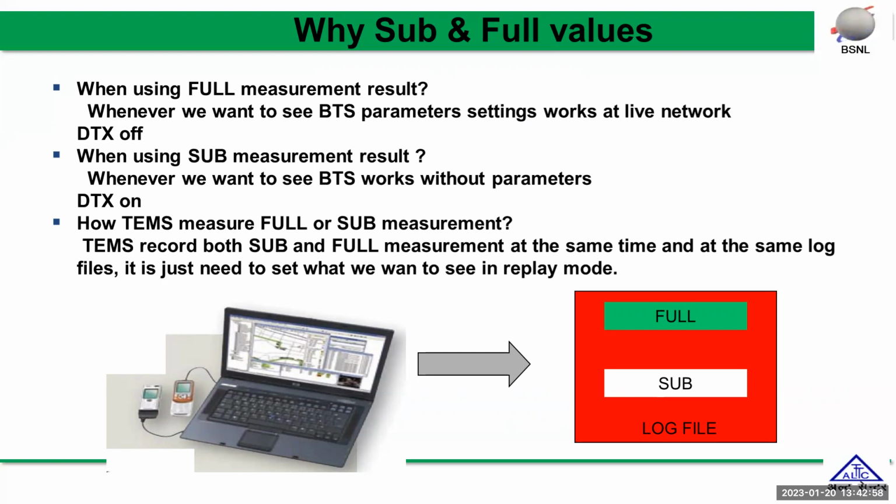TEMS measures both full and sub, right? TEMS records both sub and full measurements at the same time in the same log file. The log files that we record on the laptop during the drive test contain both the sub value and the full value. You just need to set which one you want to see in replay mode. For the thematic map in post processing of the log file, you can map whichever value you want, full or sub.